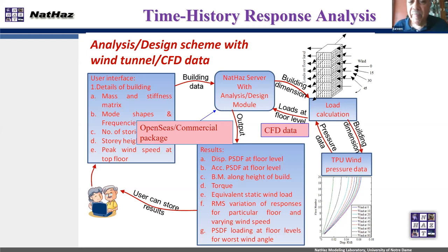Those of you who are familiar with Vortex Winds know it primarily utilizes a frequency domain approach, and also gives you more like equivalent static loads for the designers to use in a spreadsheet-type program. Now the new generation which we have developed here is purely time domain, so we can do a lot of things which are not possible otherwise.